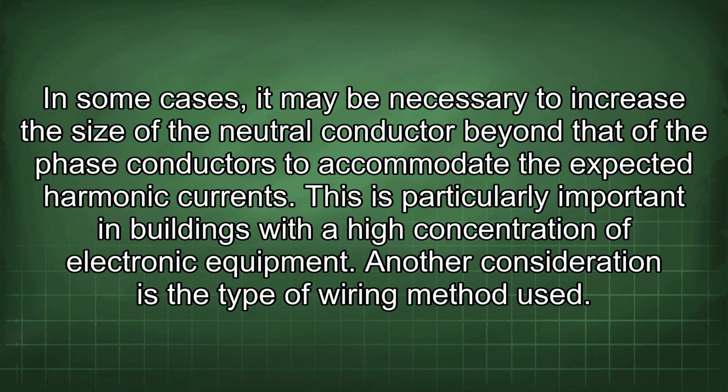In some cases, it may be necessary to increase the size of the neutral conductor beyond that of the phase conductors to accommodate the expected harmonic currents. This is particularly important in buildings with a high concentration of electronic equipment.